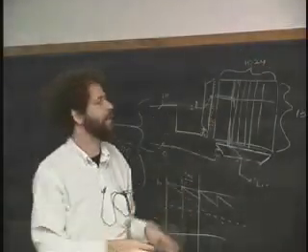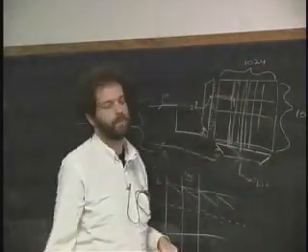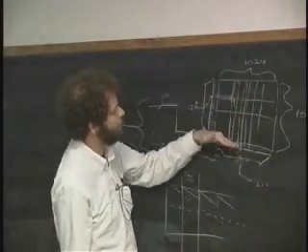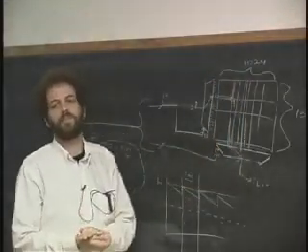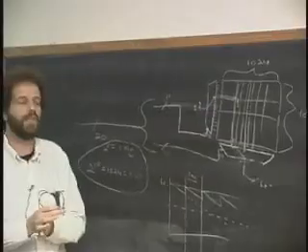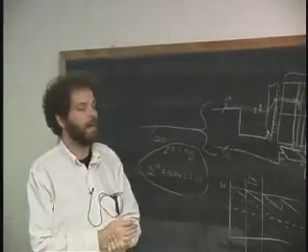There's all kinds of other tricks. Sometimes the distance is too far. They break the chip up into 4 halves. They have amplifiers here, here, here, and here, in lots of different places. There's all sorts of tricks that they do to try to get all the capacitors to act to be the same size. Yeah, it is a hard thing to do.